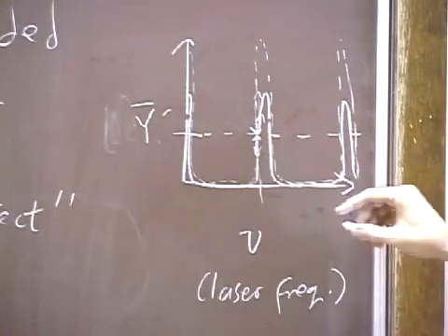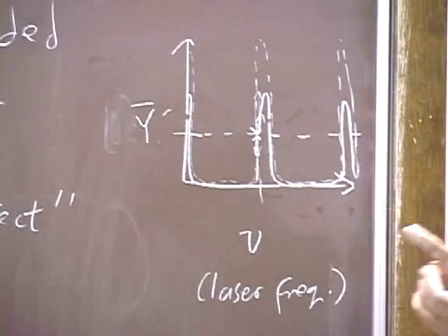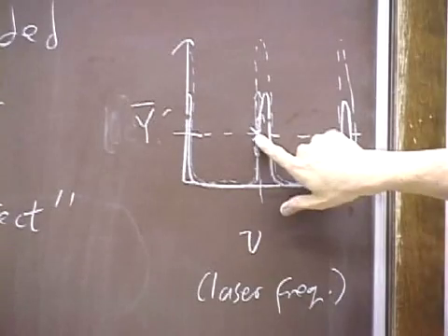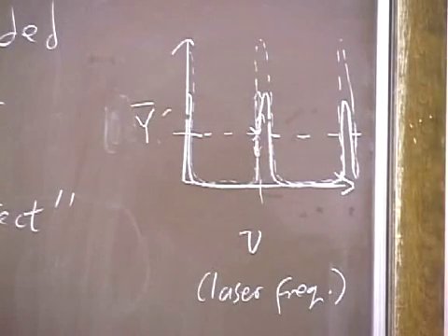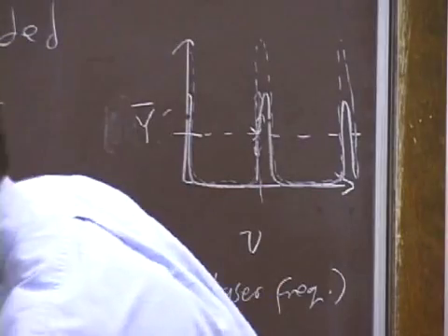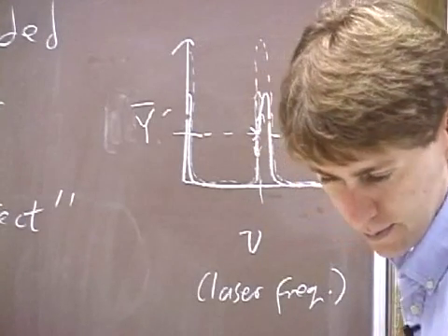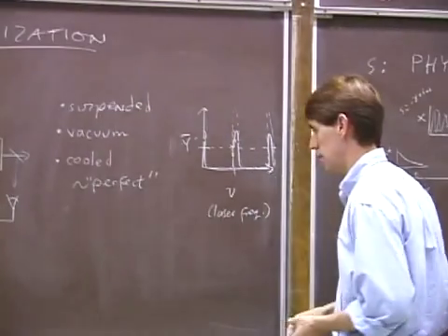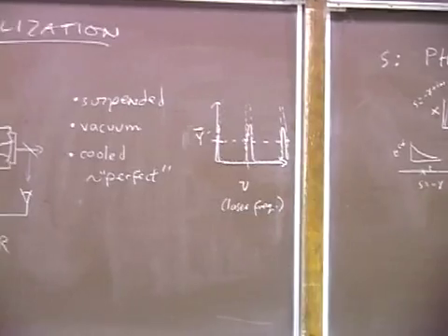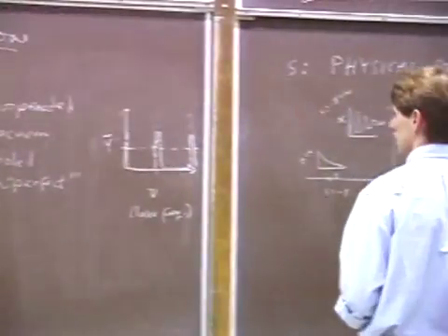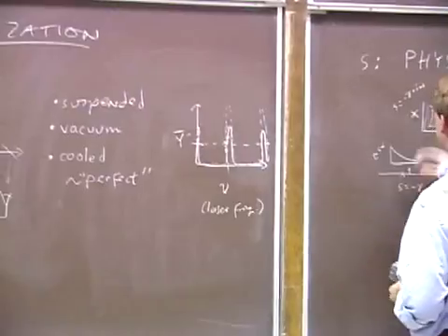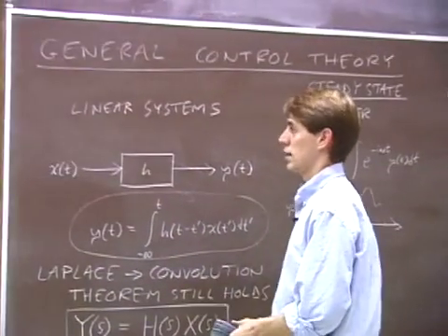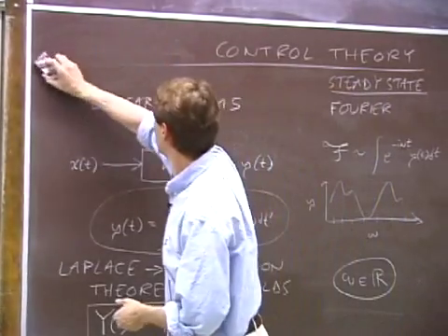And so what we've done here is we've actually introduced frequency noise into the system by coupling this intensity noise back into the frequency. And that's a problem. We need to do better than that. And the conventional way that we do that is that instead of side locking to a transmitted beam, we want to lock to 0 and hold it at 0.